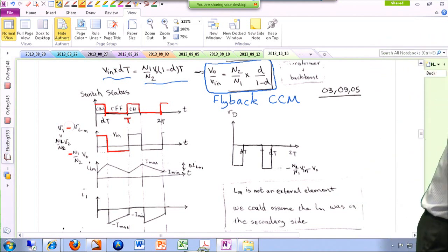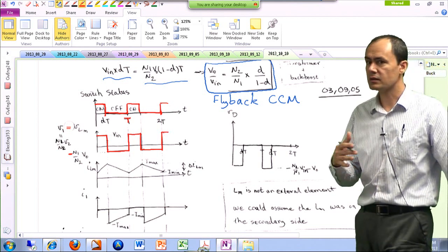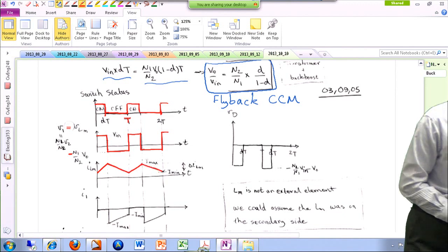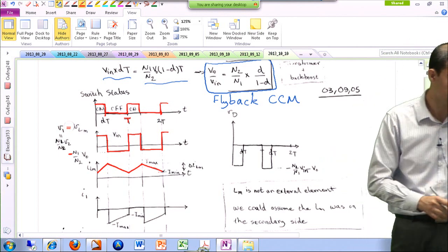And this is periodically being repeated. Okay? Positive constant voltage applied across the terminals of an inductor causes a ramp in the inductor current, positive ramp, and then negative ramp, then positive ramp, and then negative ramp. And this is between Imax and Imin.